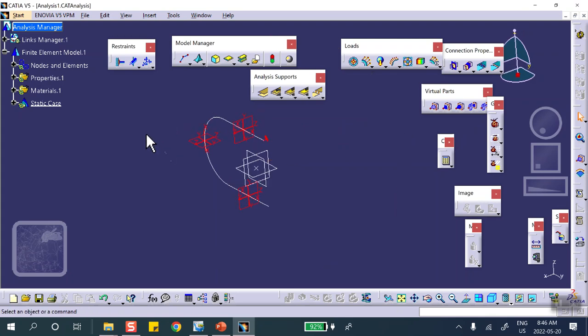By the way, let me remind you, for beams, each node has 6 degrees of freedom. So when I say clamp, that means that point does not translate in direction X, Y, Z, and does not rotate in any other direction. So you could have done, for example, if you wanted to use a user-defined restraint, check all 6 of them. That would have done the same thing.